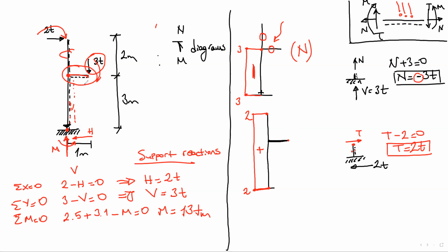Here, what is the shear force over there? I don't know the magnitude or direction. What I'm going to do, cut the system from here. Okay. Cut the system so close to this point load, but from here. Okay, let's draw it here.